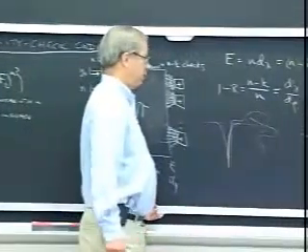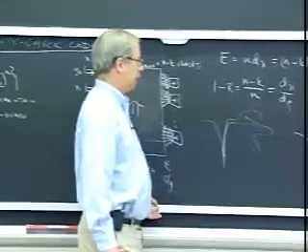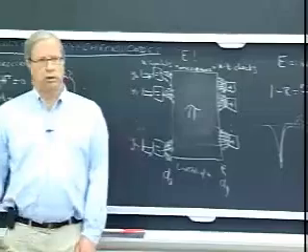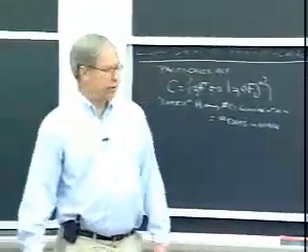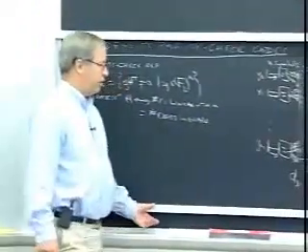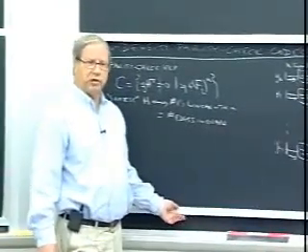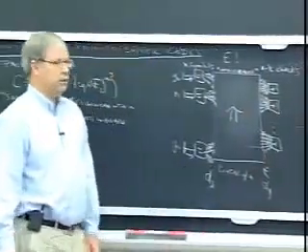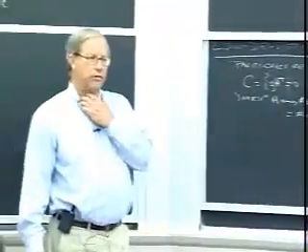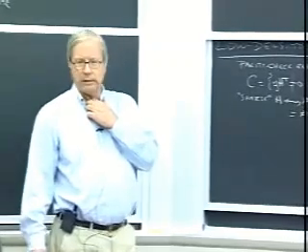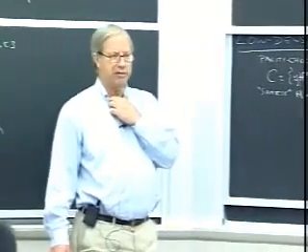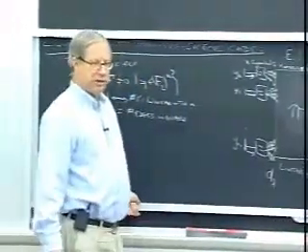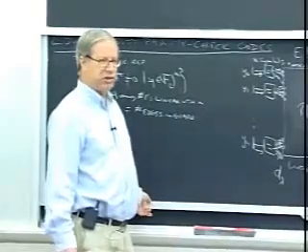So that's how it works, and it works great. And as we'll see, even with regular codes, you can get within, on the additive white Gaussian noise channel, about a dB and a half of capacity, and merely by making these degree distributions irregular, this is how Sae-Young Chung got the results that I showed, I think, in Chapter 1, where you get within 0.04 dB of white Gaussian noise capacity, and that's it. So we knew how to get to capacity since 1961 almost. We just didn't realize it.